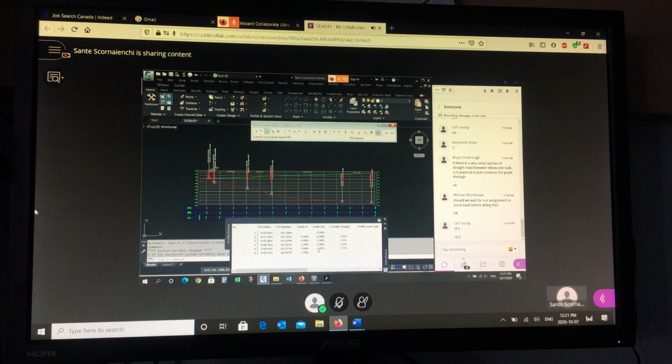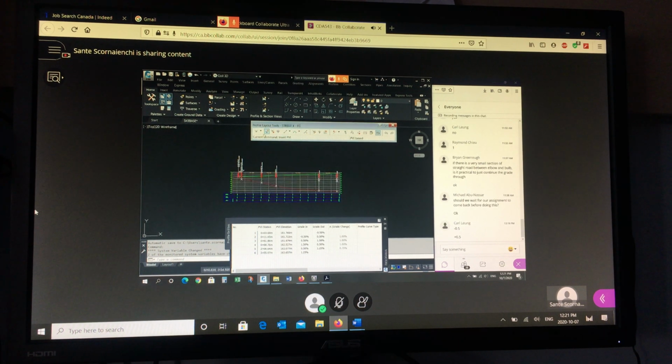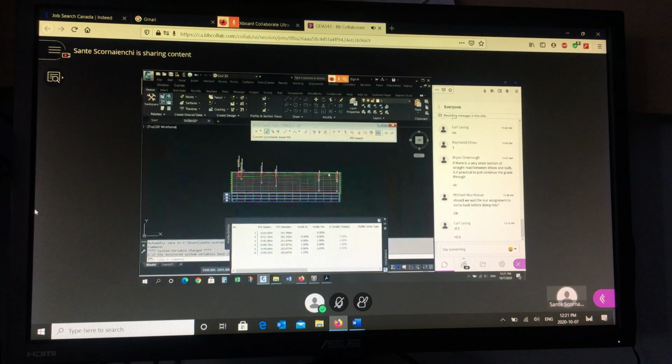Okay? So you have to have assignment 1 done. You need the edge of pavement. You got to know your bulb and your crescent location. And draw those points in the plan. Project them to the profile, connect the dots with the profile design using this tool here, and then go to the grid and change the slopes based on this design concept. This is the concept. All of you will use these same numbers, but you'll have different station locations, different elevations, depending on which site, which topo you were assigned. But at a glance, they'll all look the same.